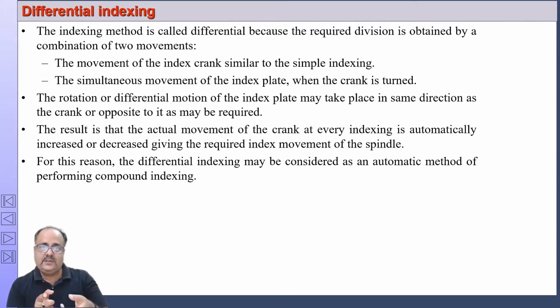Similarly, if the dial moves in the opposite direction, will it take more than 1 hour or less than 1 hour to reach from 1 to 2? You know the answers. Obviously, if it is moving in the opposite direction, it will take less time. If it is moving in the same direction, it will take more time. So we are adding certain movement and subtracting certain movement. Similarly, it works in differential indexing.